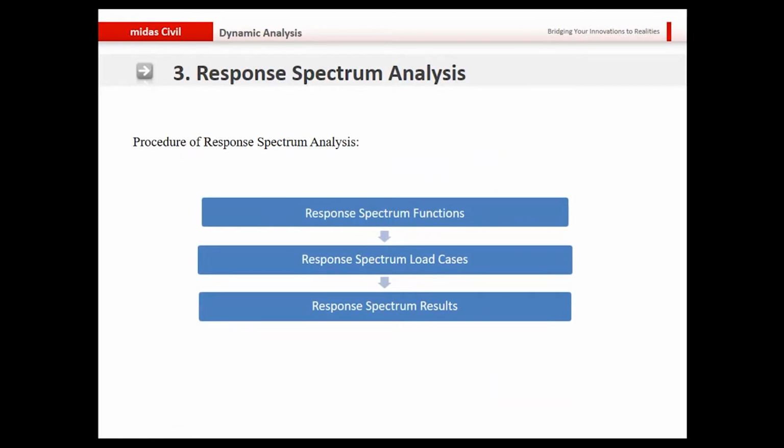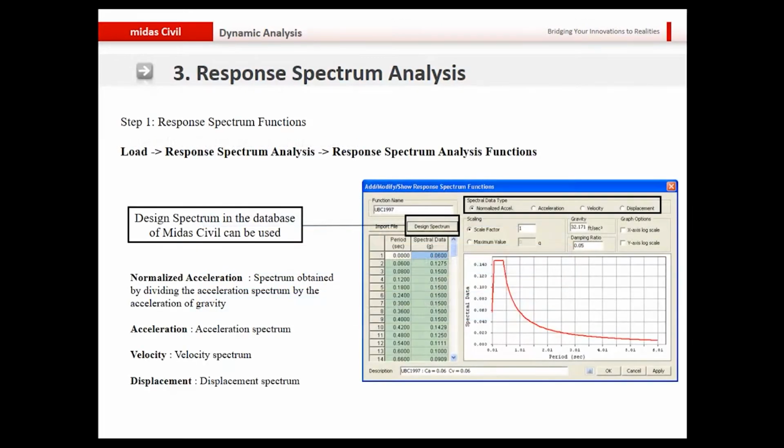For the response spectrum, you first define a response spectrum function, and then you define the response spectrum load cases. And then you obtain the response spectrum results.